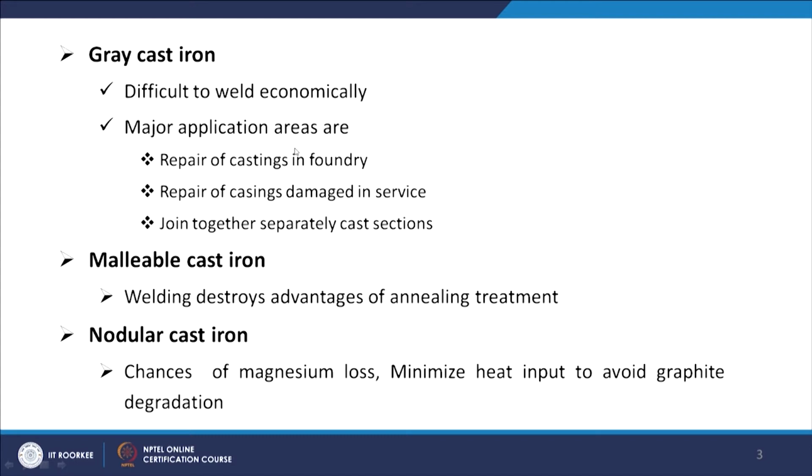When you are welding malleable iron, it will destroy that heat treatment, the heat treatment which is given to the white cast iron for making the malleable cast iron.